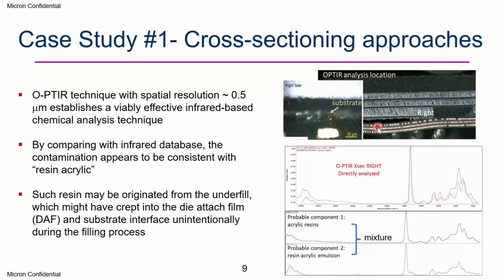And why is it a dilemma? Because unintentionally, the underfill that surrounds the neighboring unit location is actually filling into this die-attached film and the substrate. And this is undesirable. It's not the desirable phenomenon that it should be. It's not ideal for the process side. So why this underfilling happens will give the process team a need to understand and investigate. But it really finds out the root cause that underfill is causing the delamination of the units or the microelectronic parts.